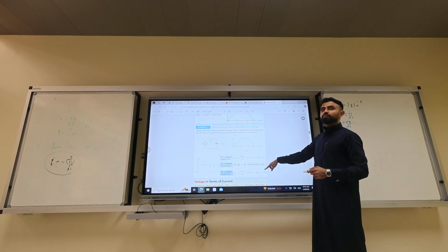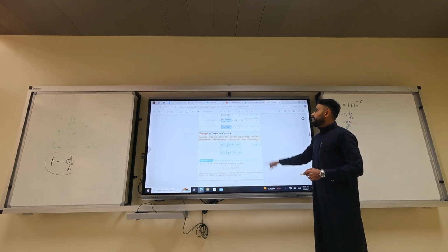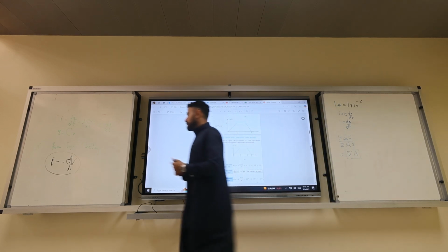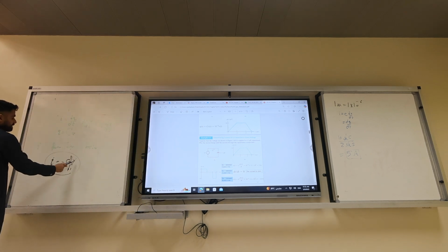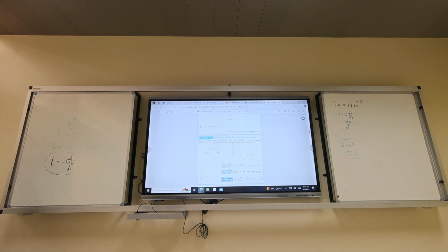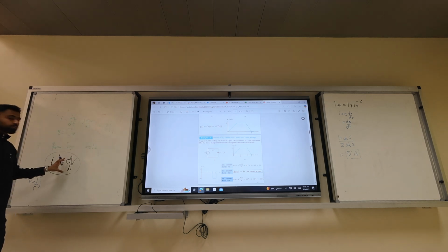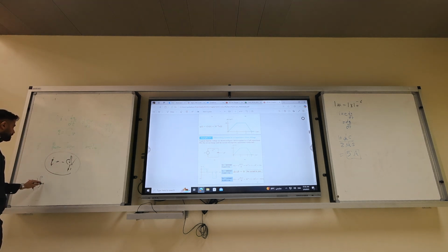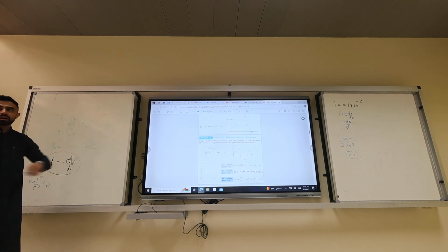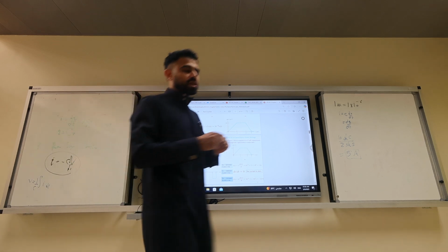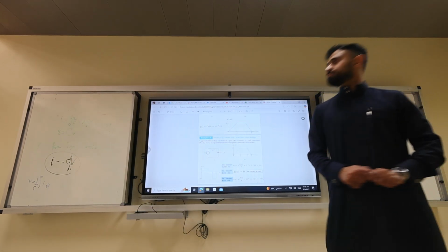Well, that's current in terms of voltage. Okay, if I tell you I equals minus C dV/dt, can you write V as a function of I? Yeah. So V would equal, you have to integrate 1 over C. I'm not using the passive sign, I'm using this equation. I'm not using the one with the negative. You have to integrate I dt. That's it. Because if you take the integral for both sides, the integral will cancel. This is a common trick in physics or mathematics.